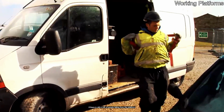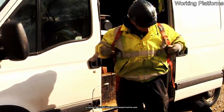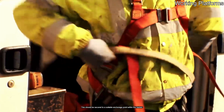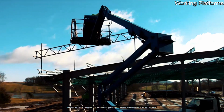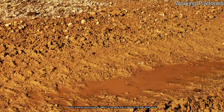If there is still a risk of people falling from the platform, a harness with a short work restraint lanyard must be used. This should be secured to a suitable anchorage point within the basket. Barriers should be placed around the platform so that falling tools or objects do not strike people below.